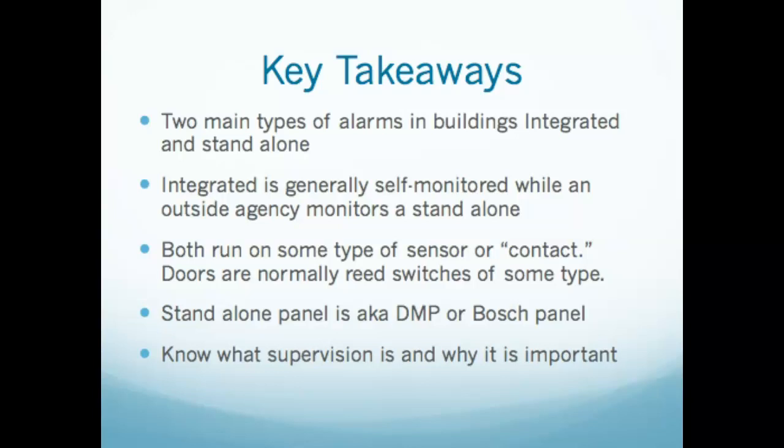If I refer to something as a DMP or a Bosch panel, then it's a standalone panel. You can call it a standalone. You can call it a standalone alarm panel. Whatever floats your boat, I'm fine with. But if you call it a DMP or a Bosch, I'll know what you're talking about, and generally anybody in the industry will. Make sure you know what supervision is, right? That resistor in the line that gives that last bit of information that says, I'm in trouble, come help me.